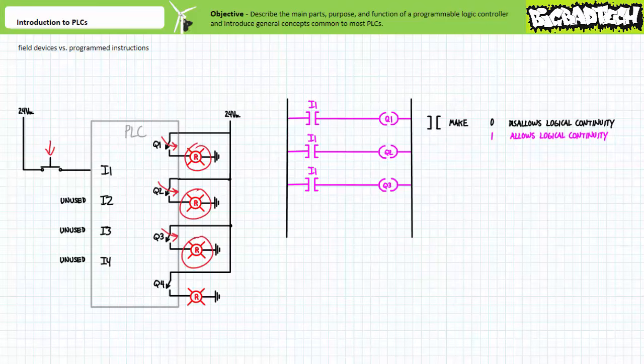The PLC energizes the appropriate output relay coils and the associated contacts close. The pilot lights associated with outputs Q1 through Q3 illuminate. This virtual replication, made possible by a PLC, saves technicians the time and trouble of physically wiring numerous redundant inputs or more expensive and bulky mechanically interlocked devices.